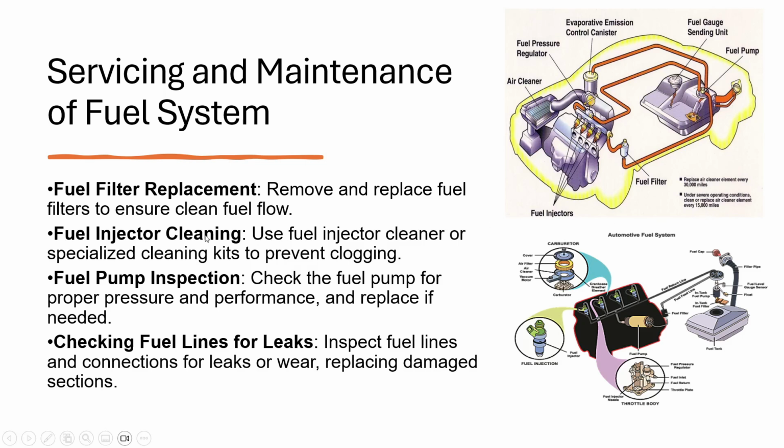Fuel injector cleaning is another maintenance activity. We have to clean the fuel injector using specialized cleaning kits to prevent clogging. Fuel pump inspection: we have to check that the fuel pump is producing the proper pressure level in order to send the fuel from the tank to the engine system. If the pumping capacity of the fuel pump is reduced, we have to replace the pump.